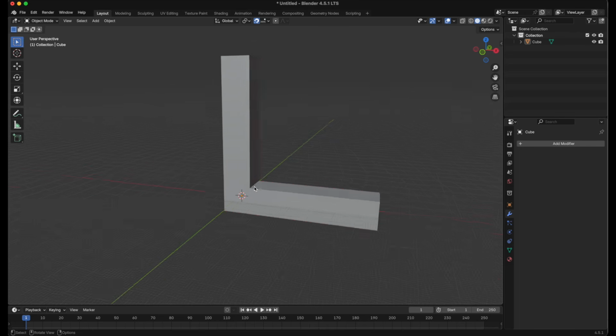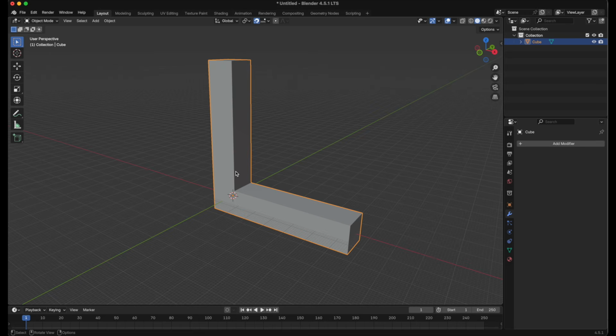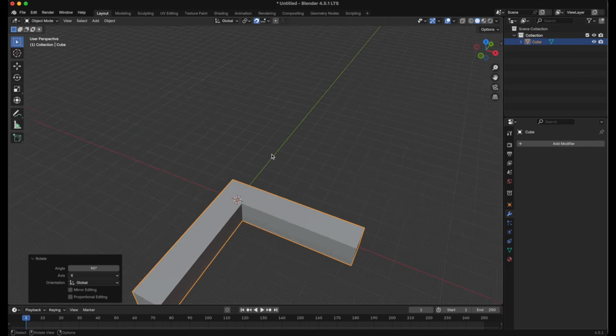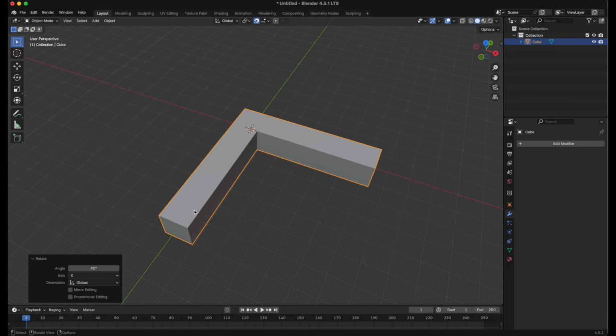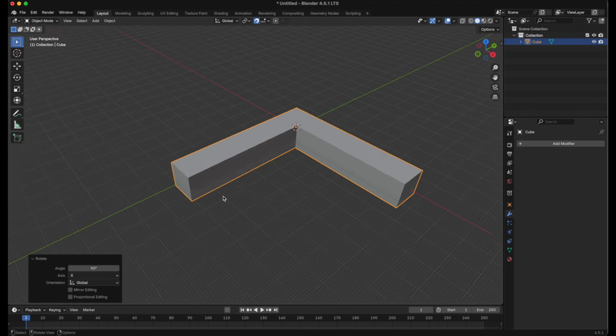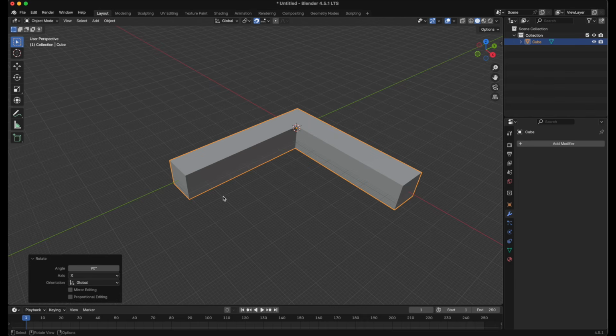An easy way to fix this is just to take the part, rotate it, and place it sideways like this. And now when the printer prints, it prints along in this direction like so. So this whole thing is built on continual flat layers across the entire part, so you avoid the stress concentration and the layer line weakness.